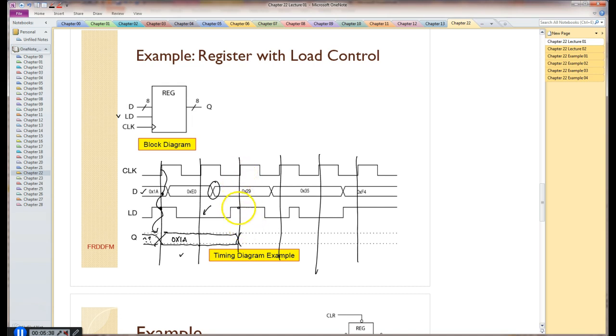Okay, next clock edge here, we do see that the load's asserted. We got a clock edge, you got data, and that becomes 0x29. Moving forward, we see next clock edge, load's turned off, so it's not going to change state. Next clock edge still turned off. And at these two clock edges, the load is not asserted. This last clock edge here, we do see the load asserted. Load's asserted there. Here's your data. Here's your clock edge. And here's your final data.